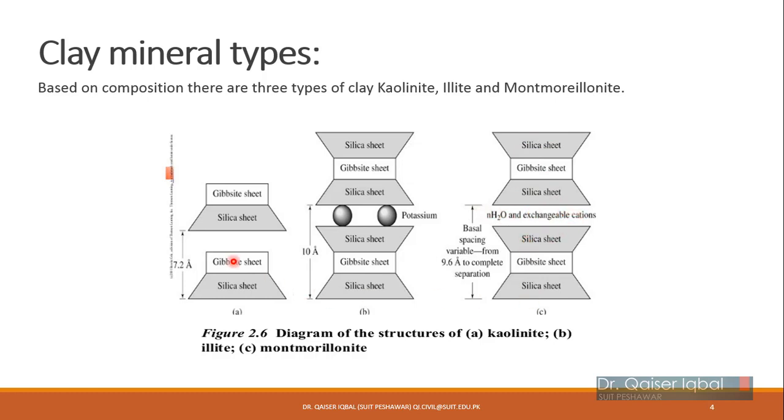Okay, so the difference is over here. Okay, over here you can see the gibbsite sheet is directly connected to silica sheet. Here the silica sheet is connected to another silica sheet through potassium atom, and over here silica sheet is connected to silica sheet, but there is water in the middle, and the size is also different of single building block.